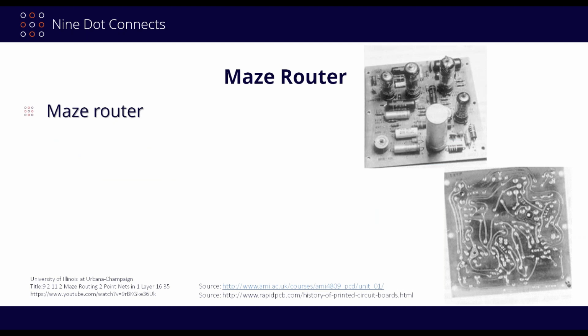So the maze router is an interesting thing because this is probably the most fundamental and the simplest router out there. It was designed by a fellow by the name of Chester Lee. That's why sometimes you may come across something on the internet that calls it a Lee router rather than a maze router. It was his concept back in 1961, and I'll give you kind of a little history here. In 1959, Professor Moore comes out with the concepts of how do we get something from point A to point B as quickly as possible along with obstacles. So he comes up with a concept paper.